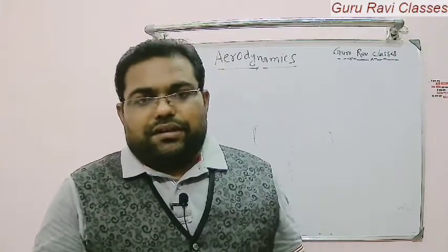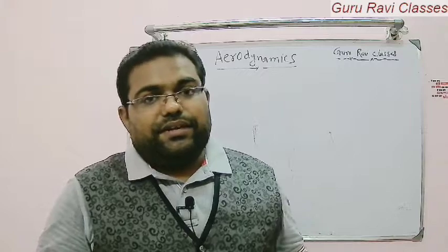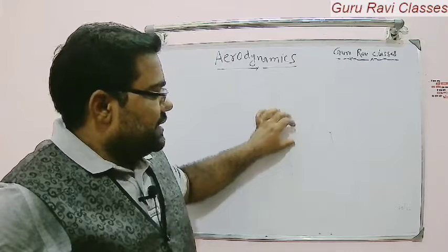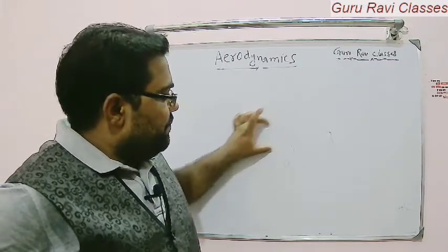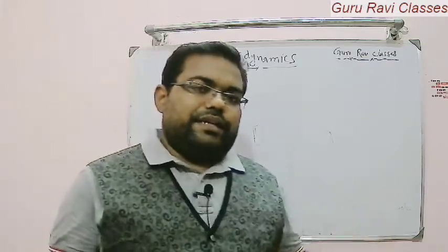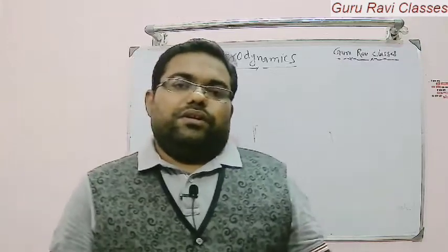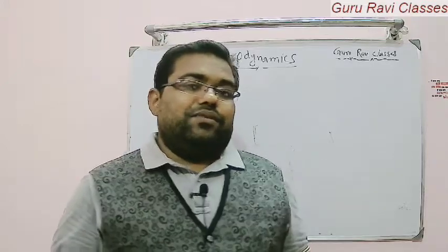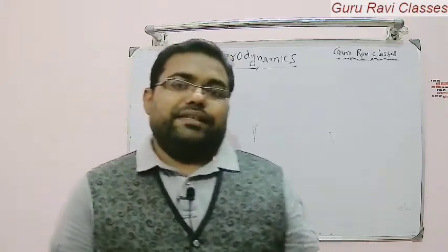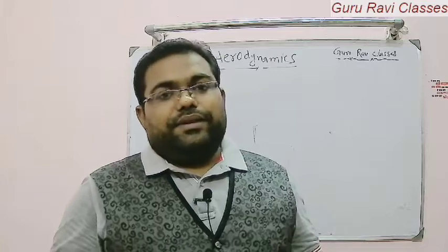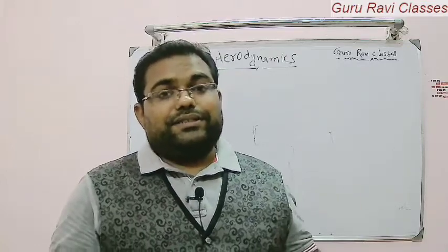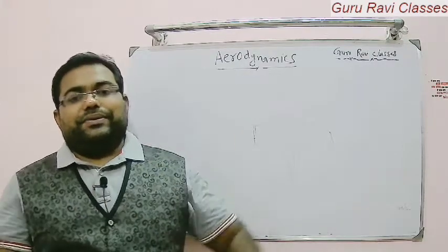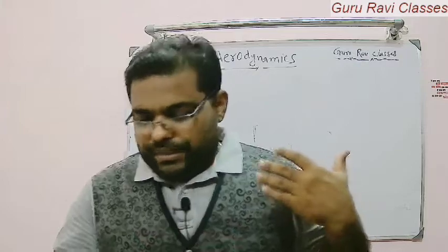Second is called gross area, right? Wing gross area. So wing gross area, basically, is where we are excluding this fuselage section, and only considering the actual wing area at both sides, and adding that is called gross wing area. So in practice, when we are working over the actual wing, we will be considering the wing gross area, but in performance calculation, we are actually considering the total wing planform area, because here the flow interacts over the entire thing including the fuselage. So wing planform area.